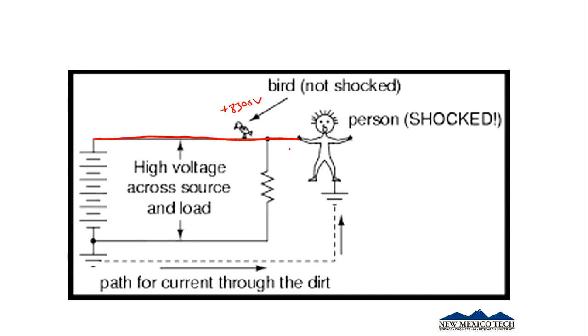Whereas when you climb up your ladder and climb out onto the telephone pole, theoretically you've got some sort of ground here, like your ladder is connected to the ground or the telephone pole or whatever. So the second you touch this, if this is 0 volts here, and this is an earth ground down here, and there's 8300 volts here, yeah, there's current flow. Whereas up here with this bird just hanging out, there isn't. Now, if he comes in and tries to step onto the little crossbar there, he will get shocked. So that's basically what's happening there.